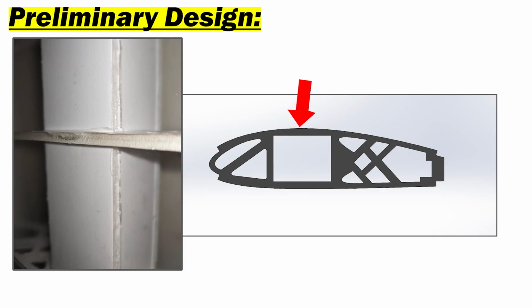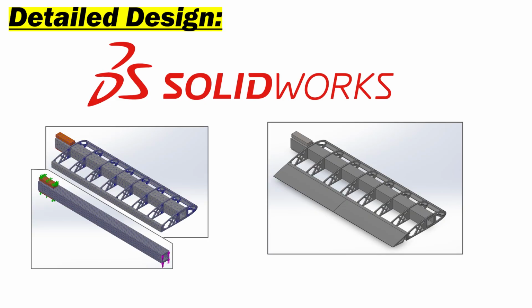It's also very important to leave enough material thickness between the edge and the ribs of the spar. Therefore, although a larger cross-sectional area for the spar may be more optimal for torsional compliance and direct stress, a smaller spar will make sure we do not compromise the integrity of the ribs when using the laser cutter, and so we will need to have a stronger internal structure that can reduce the direct stress while keeping the cross-sectional area within our limit. The use of SolidWorks allows us to simulate and experiment with more detailed and complex designs to help us meet our goals.